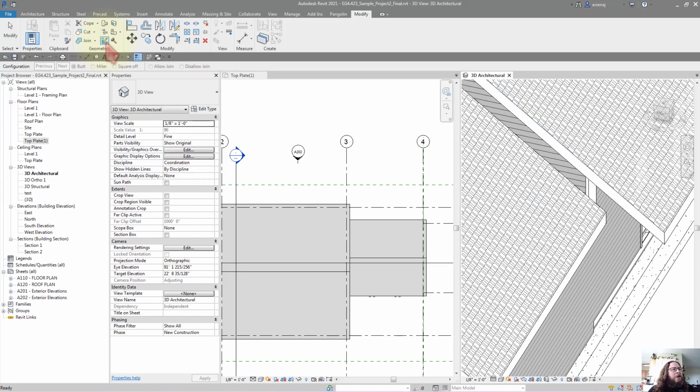So let's click this wall join, and we'll go back to our 3D view, and you can see as we hover down here at the bottom, it was showing you what the walls are it's going to join. So I'm going to hover over that, and I'm going to pick, just to get that yes, I want to modify those two joins. So I hovered over here. I'll escape out of here and do it again.